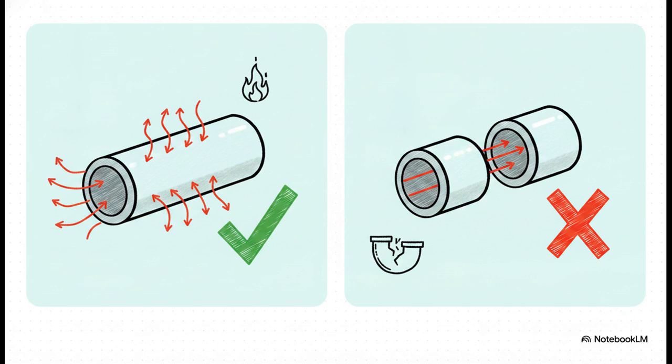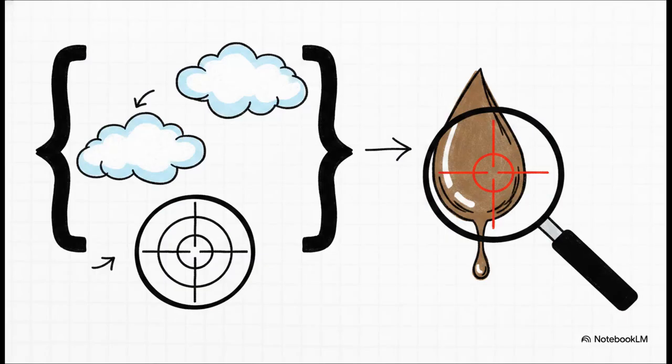The text specifically highlights this because it is such a common, catastrophic mistake. Remember, the cross-sectional area is for figuring out the mass rate of flow. The surface area is for the actual heat transfer equation. Mix those up, and you'll completely ruin your design. The charts also remind us just how critical it is to evaluate fluid properties at the precise, correct temperature. You really have to pay attention to whether a specific chart requires the film temperature or the average bulk temperature.